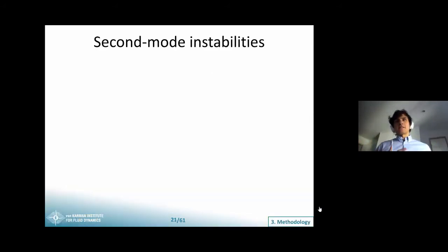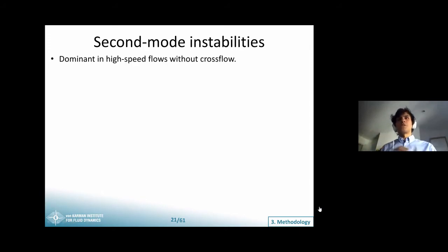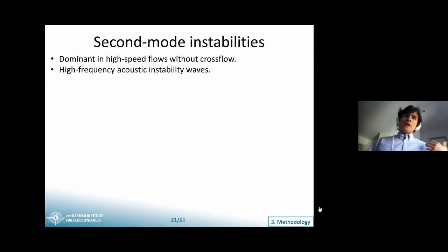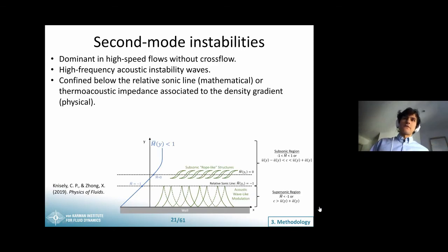Regarding the actual physical mechanisms that we are investigating, this dissertation was focused on second mode instabilities, which are known to be dominant in high-speed flows in the absence of crossflow. They are high-frequency acoustic instability waves, which are confined below the relative sonic line.